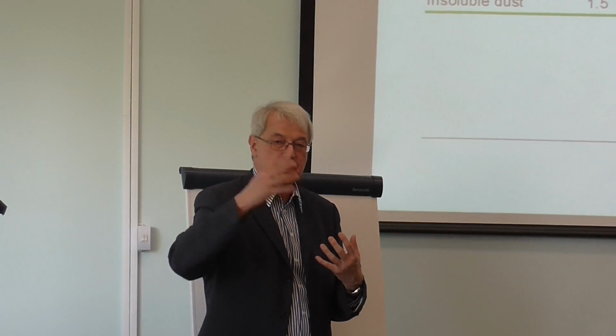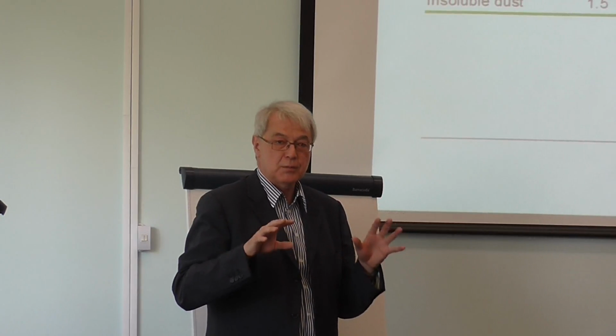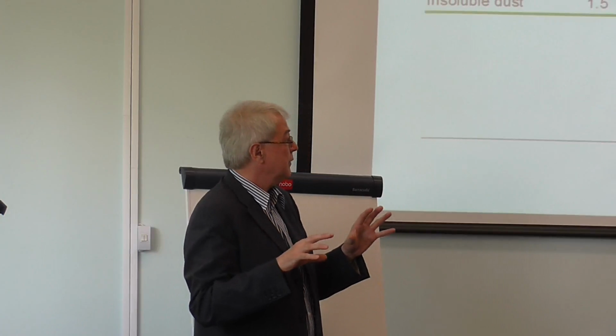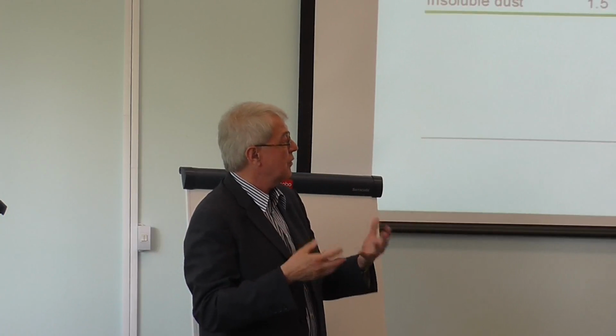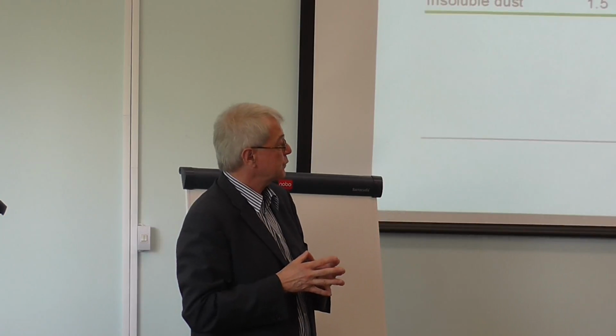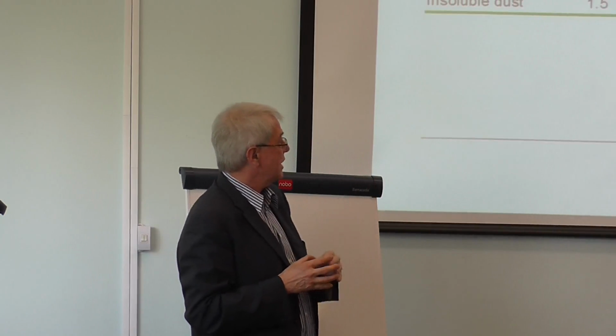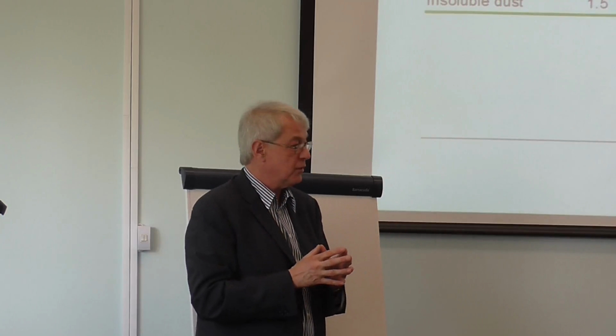So at equilibrium lung burden, you go to work, inhale, and of course you have these ongoing clearance processes, clearance and dissolution, and 1.3 grams and lower is not dangerous for particles with no specific toxicity, and concentrations delivering higher doses are dangerous. Then you can derive that for insoluble dust, 1.5 milligrams per cubic meter as an 8-hour average shift is a safe concentration.